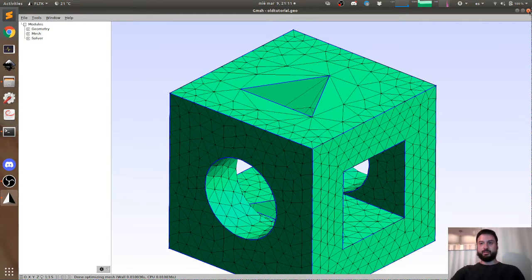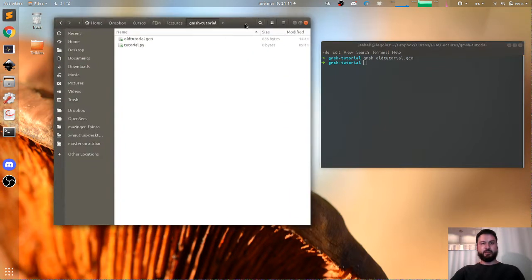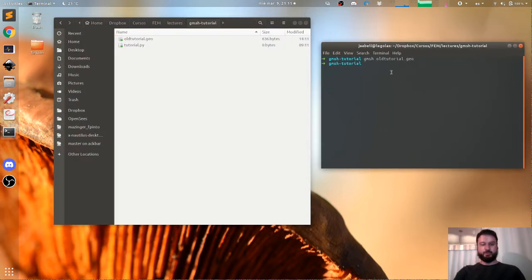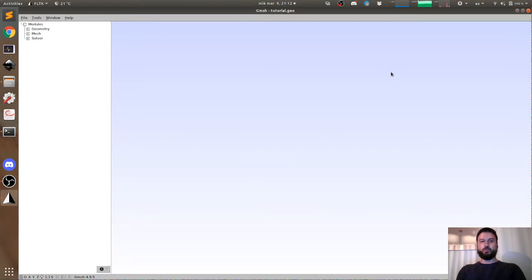Okay. So right now I'm on Linux. So the way I fire up Gmsh on Linux: after installing Gmsh on Linux, you can do something like this: sudo pip3 install gmsh, and that'll do it for you. And then after that executes, you can just run gmsh tutorial.geo. That's going to be the name of the file. On Windows, there might be something different you have to do to get Gmsh started, and on Mac it's going to be something different. So it's going to depend on your system. This is Linux, so I'm assuming that you can get to this screen, and that from here we can start.